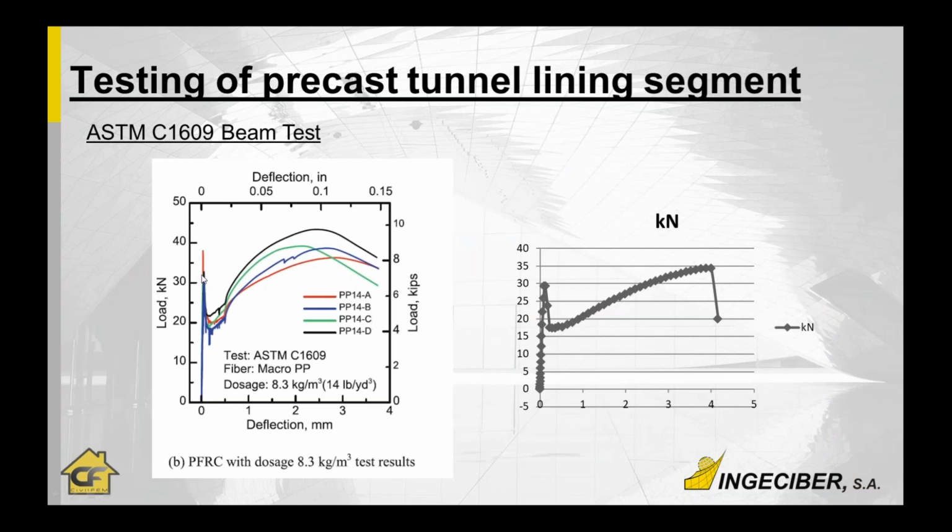Just crack stress was between 30 and 40 kilonewtons. I modified this, I added those values to be conservative, and then the maximum load on this model is, depending on the model, over about 35. So I keep this 35 and collapse at 4 millimeters.